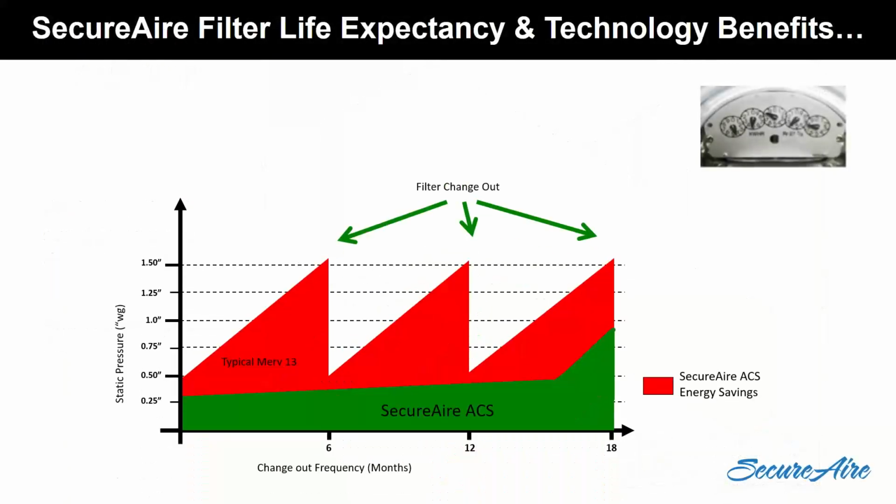The other nice thing about these guys is the way those filters load up. I don't know how to explain it, but if airflow is going that way, they kind of load from the back forward, and they use the whole density of the material as opposed to just the face of the material. So it takes longer for them to fully load with minimal pressure penalty. So you tend to get a long time out of them. This is showing 15, 16 months, and I'm probably going to want to change it. Versus my regular filtration system, I may have been changing it every 3, 4, 5, 6 months, depending on your application, obviously. But I tend to get 2.5 to 3 times the filter life on the cycle out of that thing. So yeah, you're paying a lot more for the filter because it's a special filter, but you're not changing it as often, so there's a trade-off there.